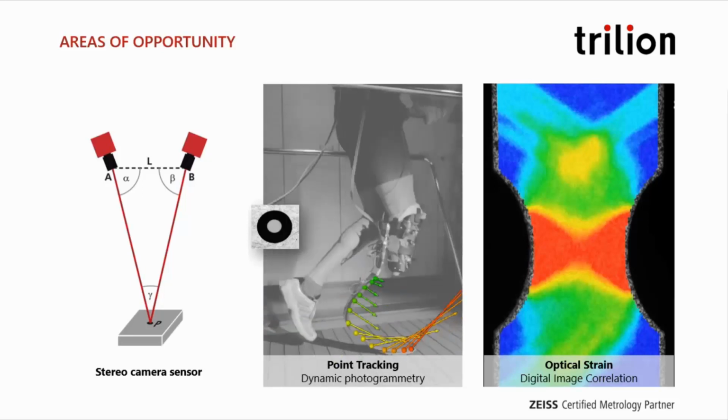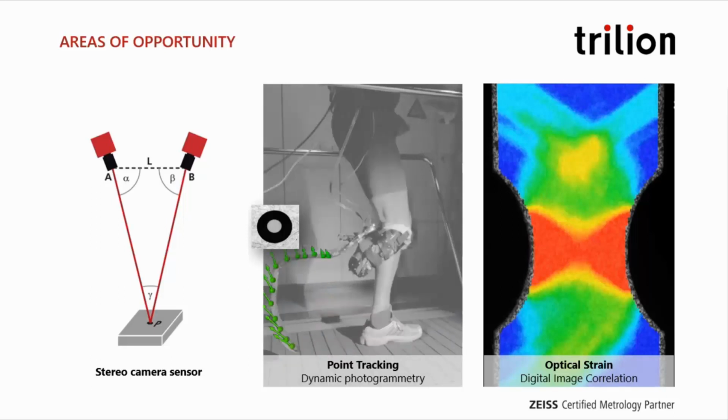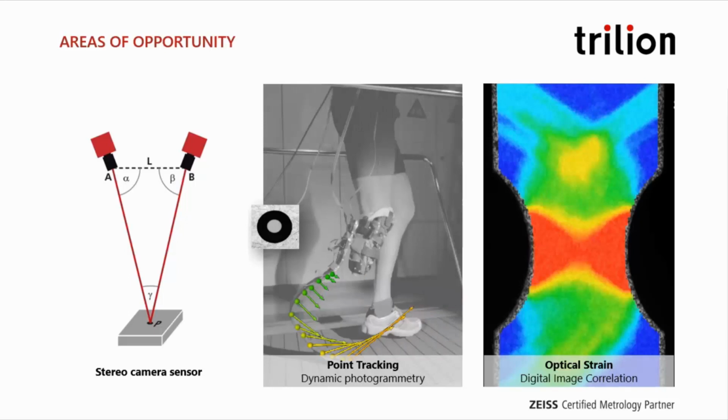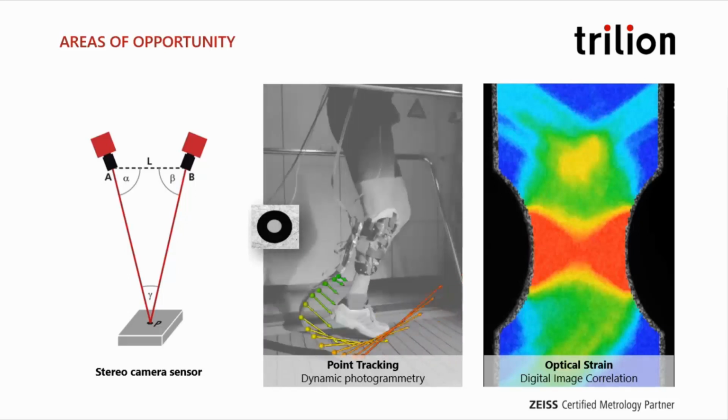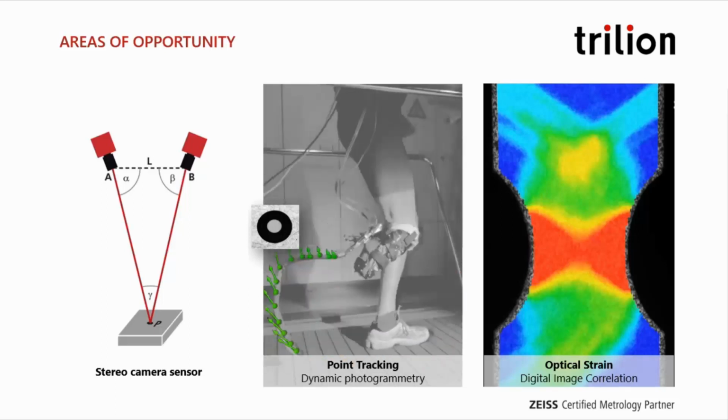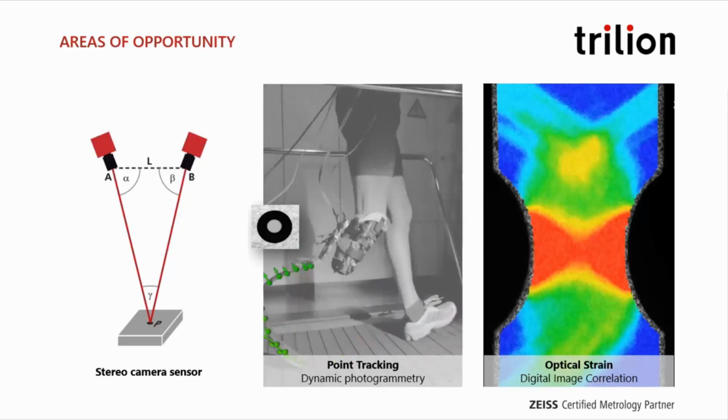Now, if you were part of this test, you know that setting up all the additional sensors to get this type of data would probably take a long time. Whereas with the Aramis system, as long as you can place those target dots, the system automatically recognizes those target dots and then tracks the displacement for it.